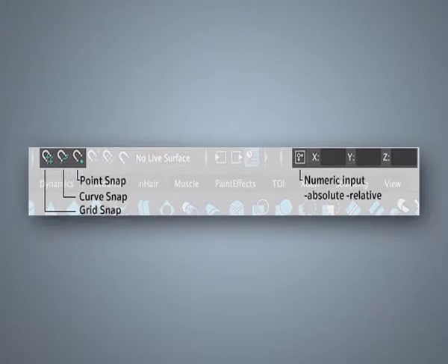That is, activate snap, press mouse button, hold while dragging along the curve. Activate the point snap option to snap to a corner or a curve. First, activate the display of the corner points: Display, NURBS, Edit Points, and activate snap. Press mouse button and click on the corner of the curve.